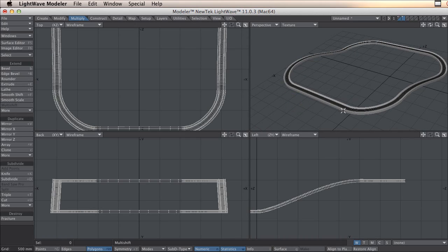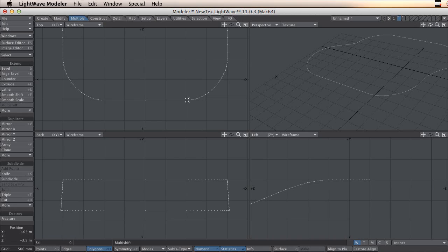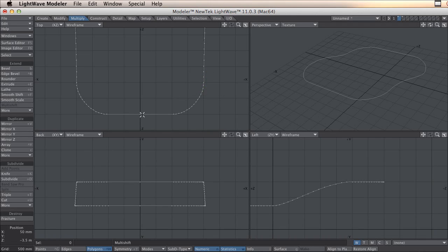The next thing to do is make a new path, and the reason for that is if you go back to the original path, you will see that the space between each point is not uniform. So if I'm going to make a car go here, it's going to go very fast here and very slow here and a little bit faster here, and it's not what I want at this time. So I have to make a new path with uniform spacing.